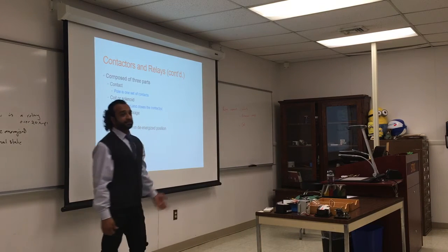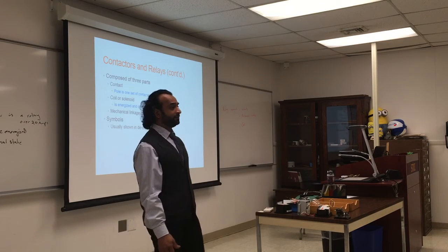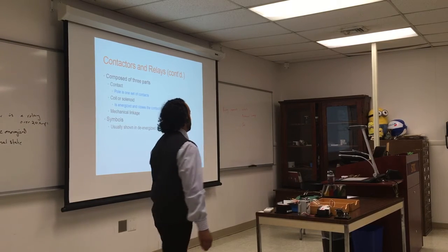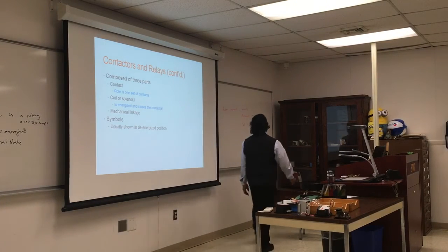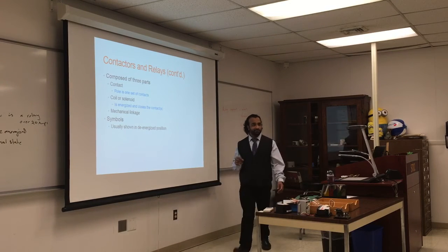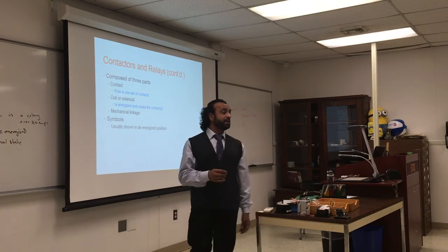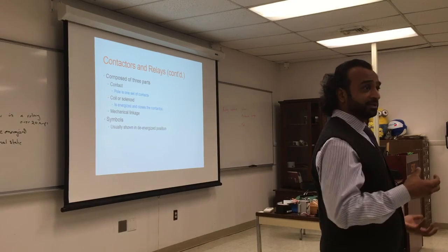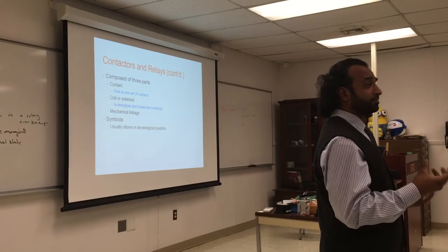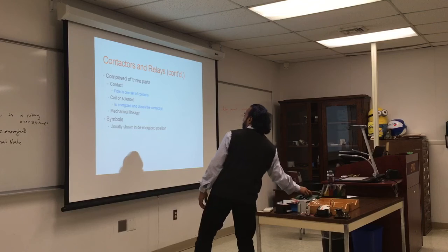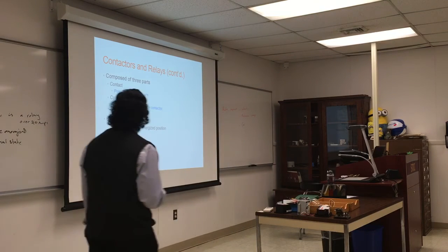Do we fix contacts or relays? No. Why would you do that? You replace them. We clean the contacts sometimes, but you can replace some parts. Some of those contacts are very expensive on relays because they're vacuum sealed. They don't want to oxidize and so on. So these are some of the issues.